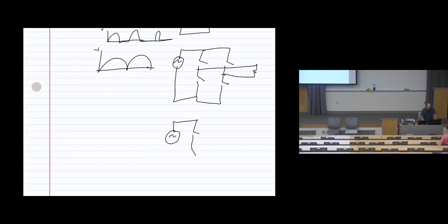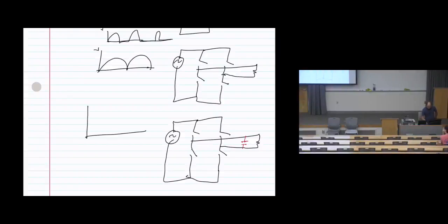We keep the same design, but we add another component. Here is the resistor, so we add a capacitor in parallel. The capacitor will charge and discharge. So the waveform will go like this way. Here's the voltage. Then since the waveform is supposed to go down, the capacitor will not let it go down this way. It will go down only a small amount, because the capacitor will discharge.